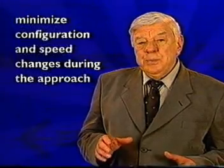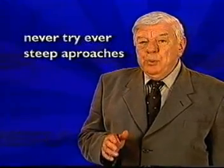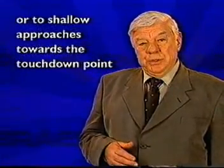Minimize configuration and speed changes during the approach. Most important of all, if, when on final approach, the aircraft is found not properly positioned, never try steep approaches or too shallow approaches towards the touchdown point. And never, ever do it powered off.